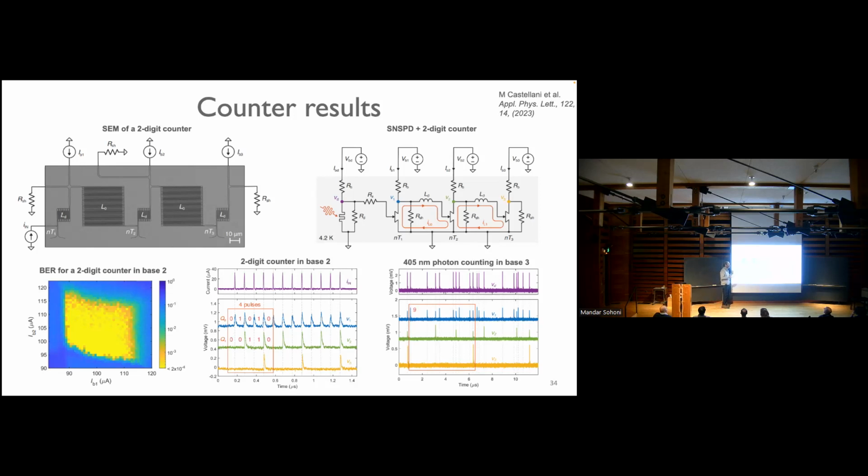It's like 10 charge carriers per cubic nanometer. That's the number. And as a result, to carry 100 microamps, these charge carriers have to move very fast. Whereas the drift velocity in silicon might be, I don't know, a centimeter per second or less, in these systems it's like 10 meters per second.